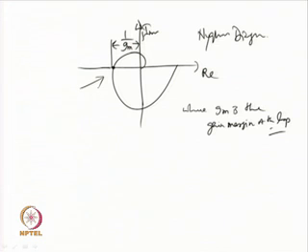Now, the magnitude of the loop function at this phase crossover frequency, because what is the frequency at this operating point? We have got the phase crossover frequency, because the phase angle is minus 180 degrees, negative real axis. Please keep in mind, this is the negative real axis and the plot is crossing the negative real axis.